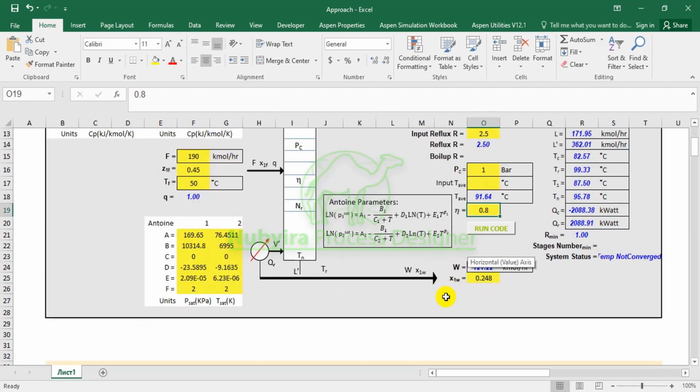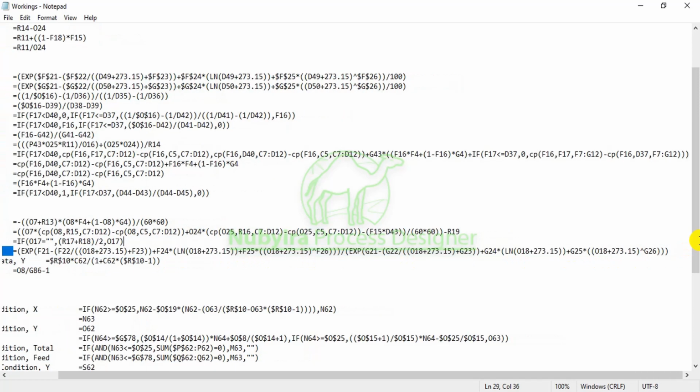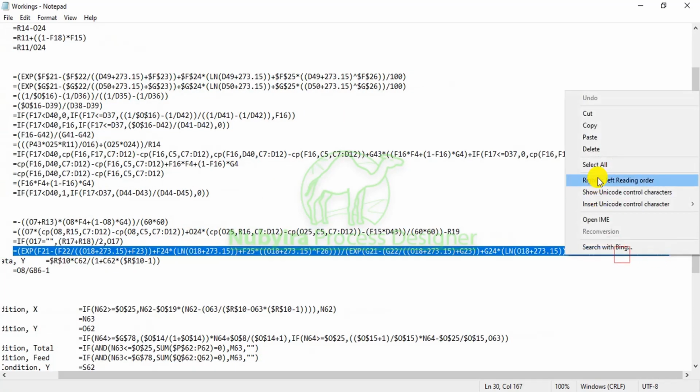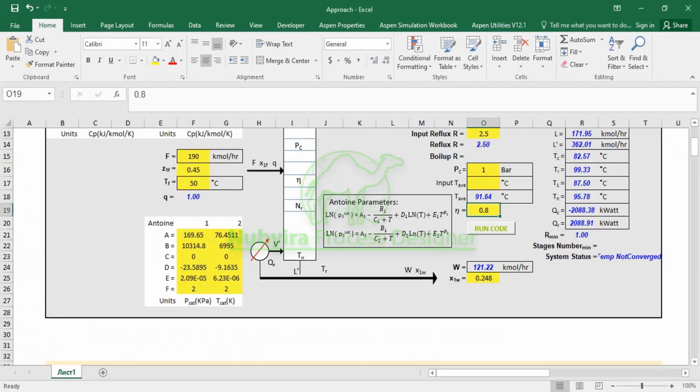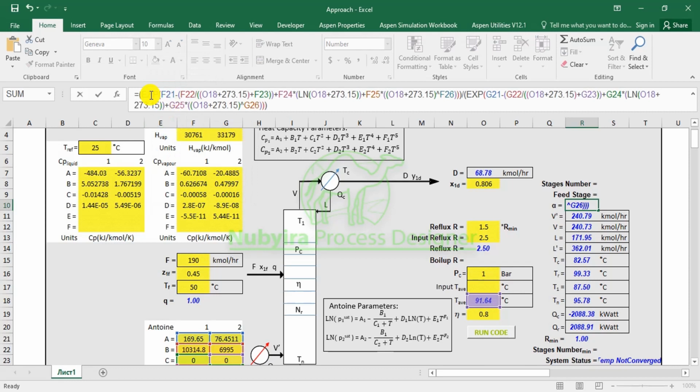Then the formula for the relative volatility, like I said, P sat. I have to write the equation like the one that we have been doing. We write the equation out, but it's going to be based on the average temperature, because it's in logarithm.